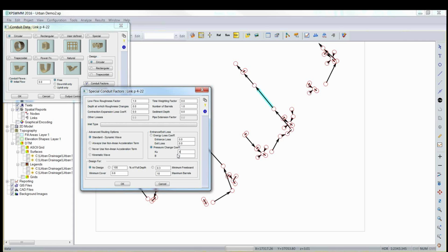So that's a process that we're looking to improve inside our software to give users the flexibility of a dynamic pit loss arrangement, where at low flows the loss may or may not be as high as it would be under higher turbulent flow situations. A really good reference document for people is of course the Missouri charts. You can also go to the appendix of the Queensland Urban Drainage Manual, and also a reference document by the good John Argue from South Australia, and roughly the name of that document is the Stormwater Drainage for Small Australian Urban Catchments. Another really good reference text.